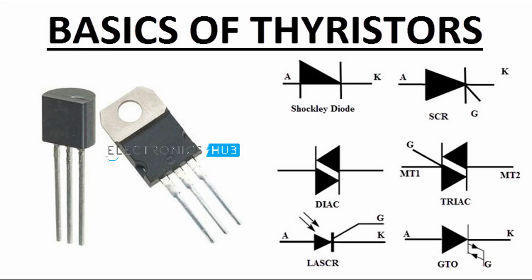Slower switching speed. Although faster than traditional SCRs, SCSs are slower compared to modern semiconductor devices like IGBTs and MOSFETs. Example application. Pulse generation circuit. In a pulse generation circuit, the SCS can be used as follows. Initial state. The SCS is in the off state, blocking current flow.